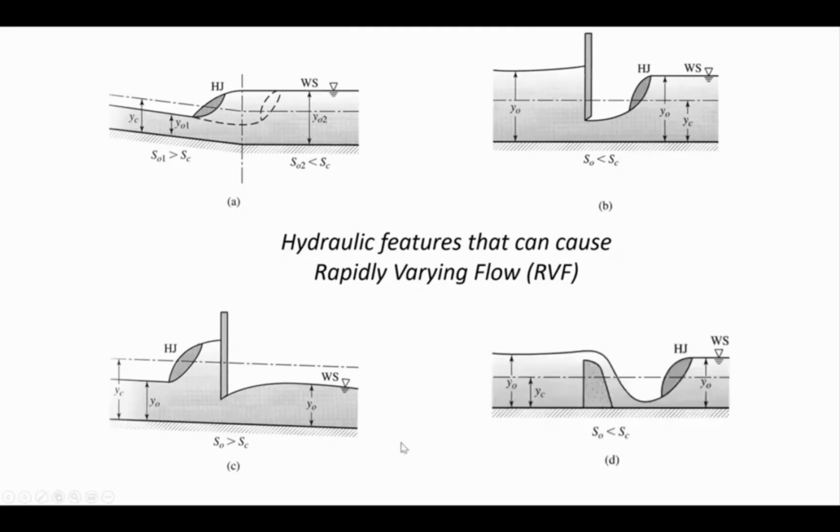And finally, we talked about spillways already. The flow that's coming down the front face of a spillway gathers quite a lot of velocity, and because of that, dropping from the top of a dam back down to the river below, it picks up enough velocity that it's moving supercritical and the water has to go through a hydraulic jump. We're going to watch a video in a moment that talks about this, and how the water is moving so fast that it can damage the stream. It has a lot of velocity, and there's energy there that could cause scour.